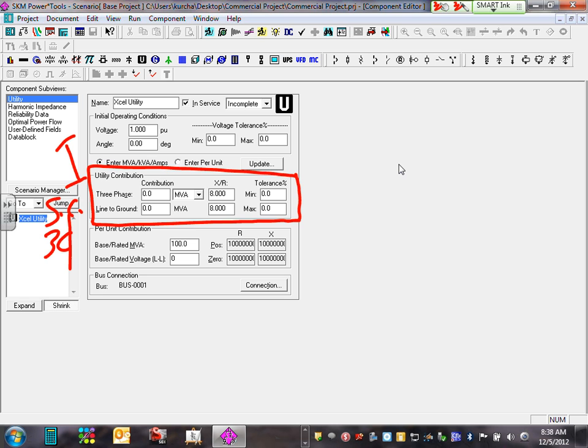So we need to go find the short circuit for this transformer. For this component, all you need is just these 2 values. Actually, this value here and this value here. Let me tell you how to calculate them if you don't have it. You don't need to do what I did, but follow along with me. You need to find the I short circuit. Here's what I do, guys, for I short circuit.